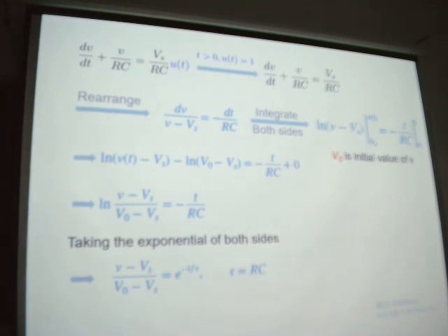What is this one? Time. This one we call the time constant. Have you ever heard of the time constant? From the name we know the time constant is something about time, right? That means the unit is second. Here we can see it's r times c. If we compare the units, we'll find that if we multiply r and c together, the unit will be second.